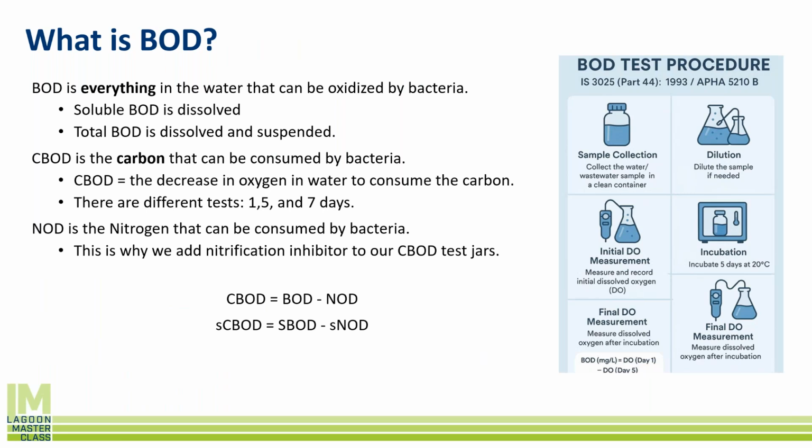A small twist on BOD, and some of your permits will actually say CBOD on them. So depending on your state, also depending on your watershed, you could have a BOD permit or you could have a CBOD permit. CBOD means that we have just carbonaceous biological oxygen demand. So really what we're trying to measure there is just the organic carbon. So it's a different kind of food. So we're trying not to measure any of the nitrogen or the nitrogenous oxygen demand when we do CBOD.